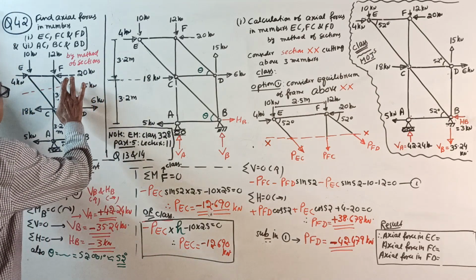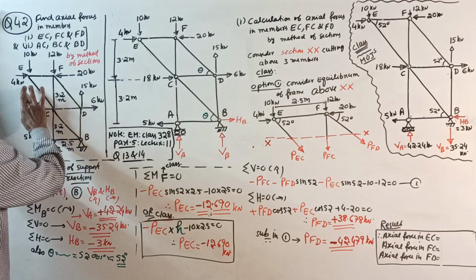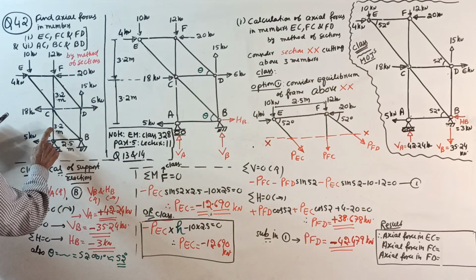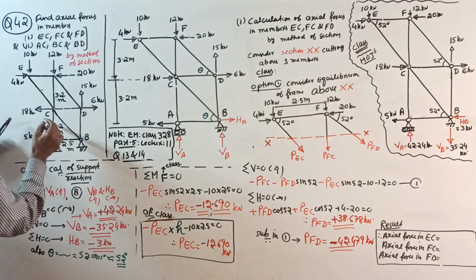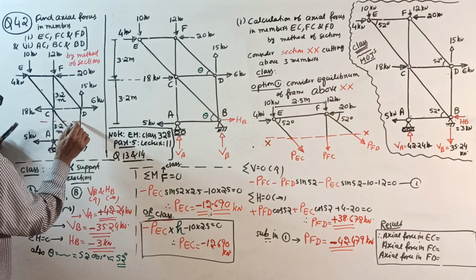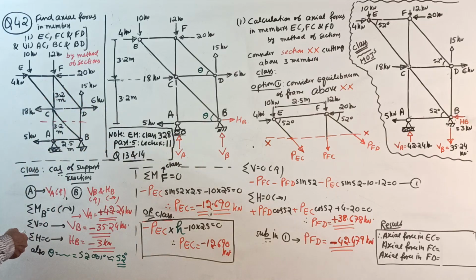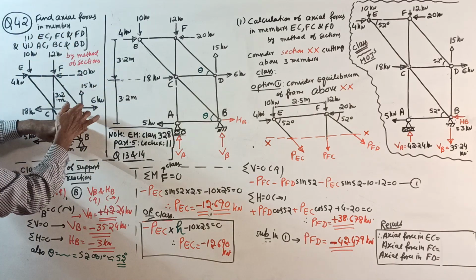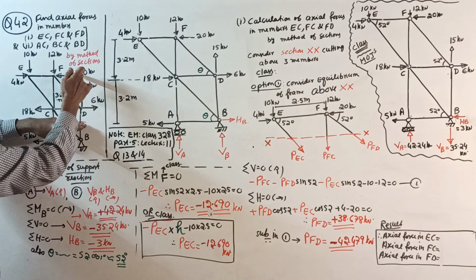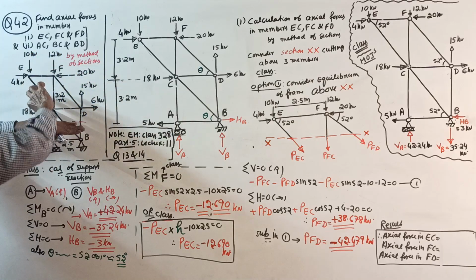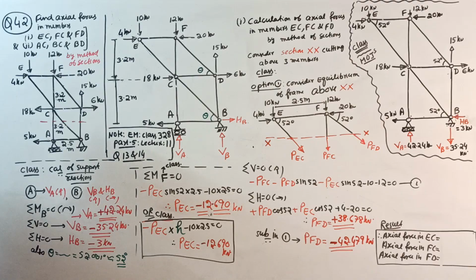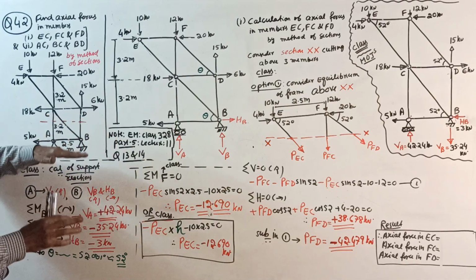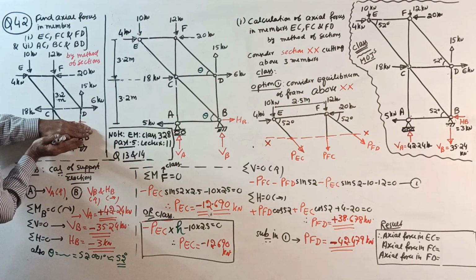Now next, another question here on the same frame: AC, BC and CD. Make it out here. Cut here. Now, if you look at the upper side, 3 unknowns are there. Forces are a little more, okay, no problem. Moments are direct. Again, if you look at the upper side, we should make a note: support reactions are not required. See here, not required.